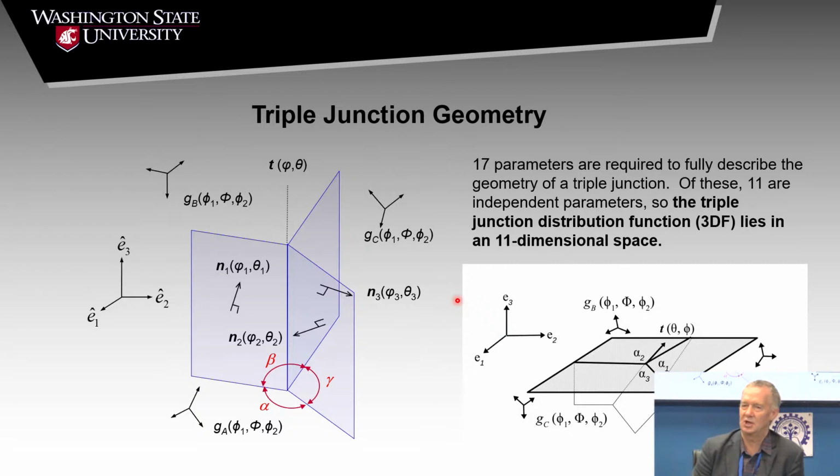So this is looking closely at a triple junction, and this is being very idealistic on what a triple junction would look like. If you cut through a section plane and you see a triple junction, you don't know which way that triple line is pointing, right? In this case, it's coming out at an angle, and for all those boundary planes, you're not showing which orientation those are by looking at the plane. You can look at 3 dimensions, right? We do that sometimes, but then we're very limited on how much space we can look at, right? And we'll talk about why that's a problem.